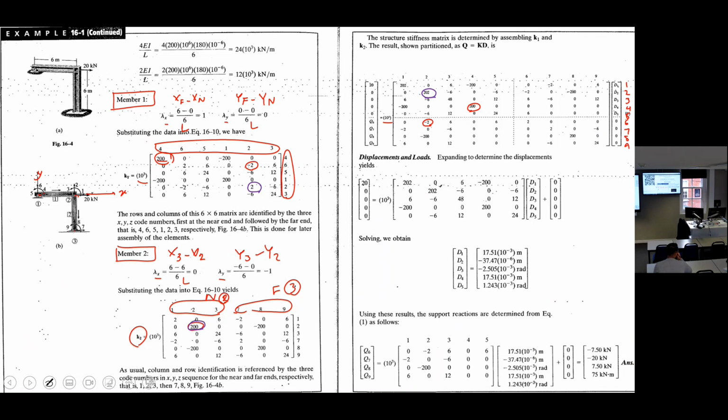Is there any physical interpretation for this? I did the physical interpretation last week for another example in B. There is a clear interpretation when this happens. A single cell receives two different numbers from two matrices. These two matrices are from element number 1 and element number 2. Degree of freedom number 2 is the vertical deformation of node number 2.